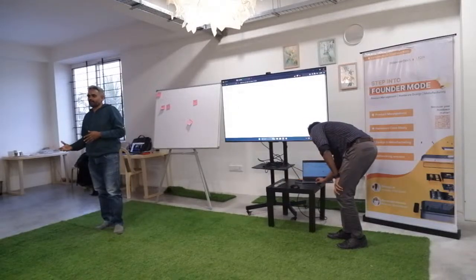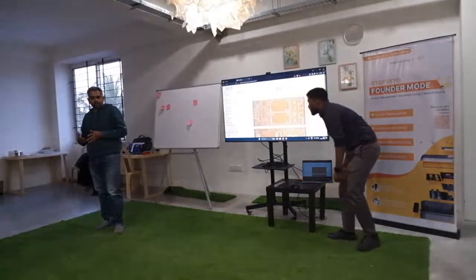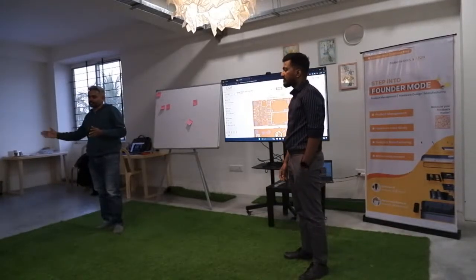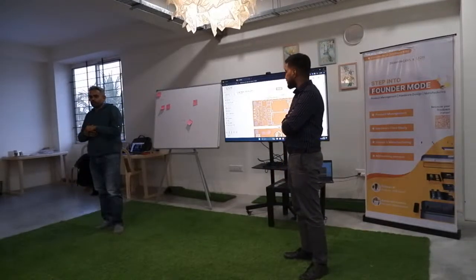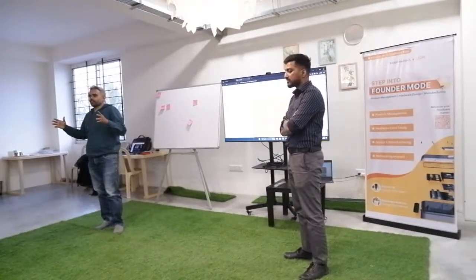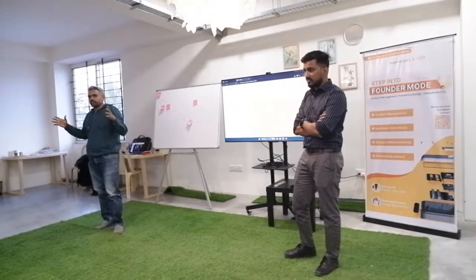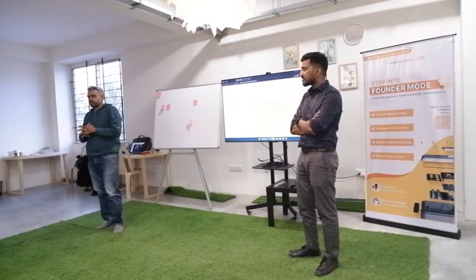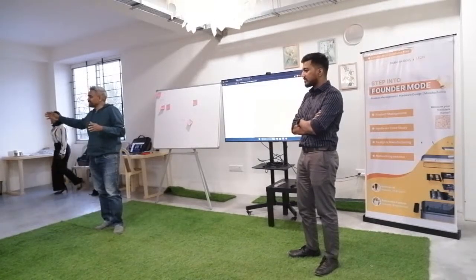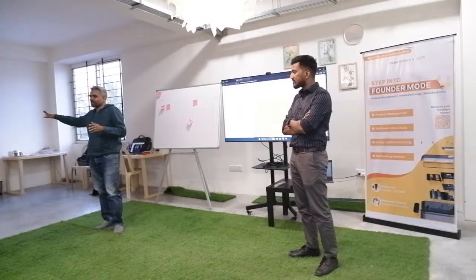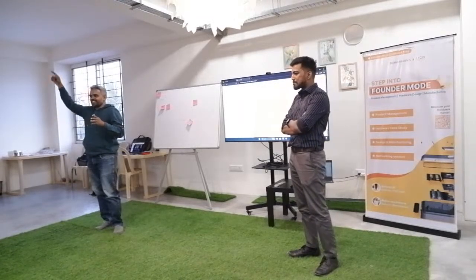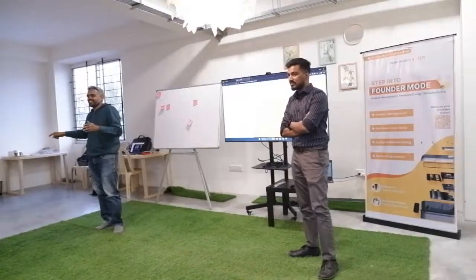Especially PCB manufacturing: a two-layer board easily has 20 to 25 different processes. So we have fairly automated most of it, so that we have tighter quality control and tighter time control also. But let's say you are doing this, and on an 18th or 19th process, something goes bad. You have to discard that and restart again from the first, right?